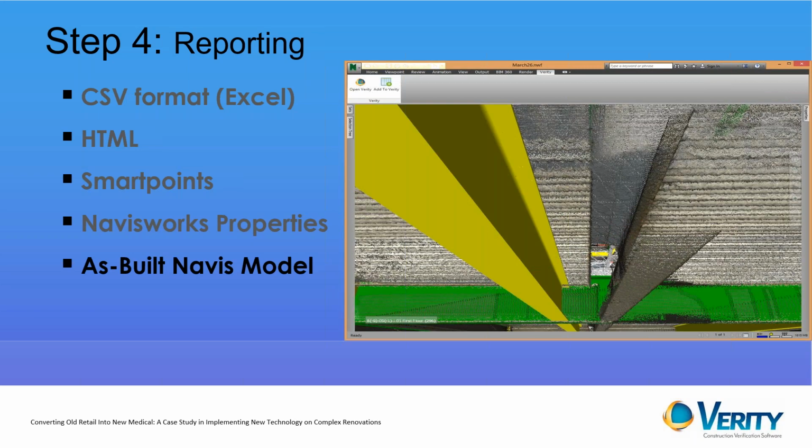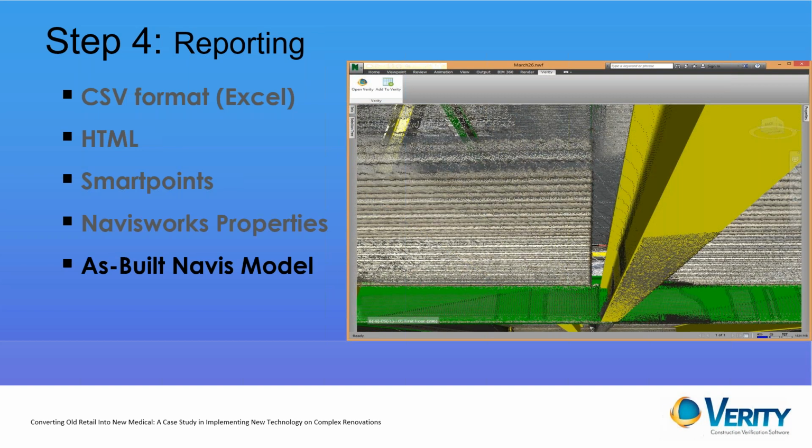And then my favorite, we can actually as-built the Navis model. This is really useful for instance, what Jacob was doing, because even though the engineering model might have things sloped, we can actually translate and rotate the geometry into place in Navisworks so that you can run your clash against the flat object. You don't have to wait for a cycle and get a new model from an engineer. You can just immediately get to work on those as-built conditions.